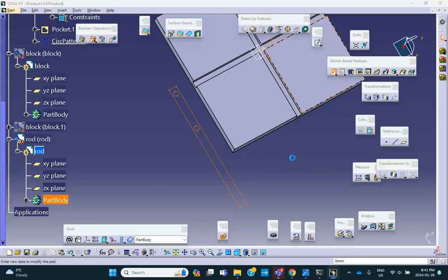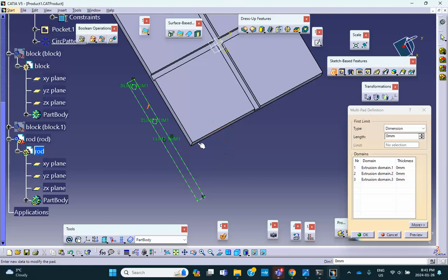As far as the mechanism is concerned, it doesn't matter whether they're holes or actually pins, but it looks nicer if I make it a pin. So this is going to be the whole periphery. I'll make that thing maybe 3 millimeter. This one is going to be more than 5, so I'll make it 6 millimeters. So 3 millimeters are going to be the height of that rod, and 3 millimeters sticking out.